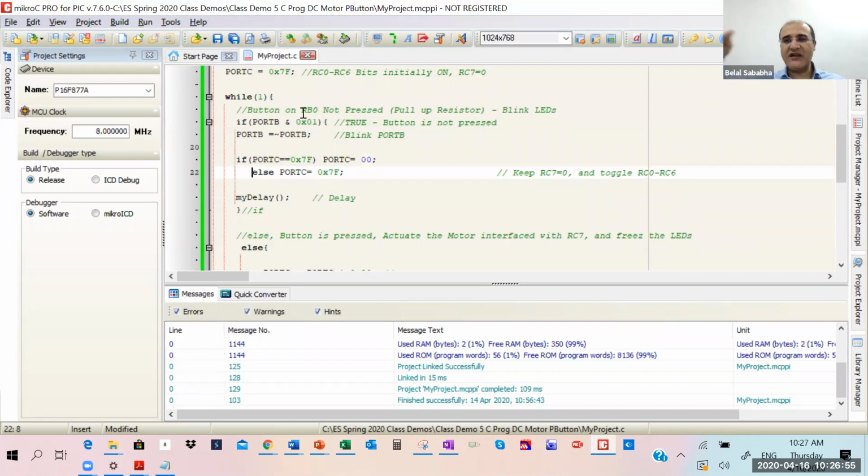So if you keep your finger on the push button for a long time, that allows the program counter to finish all the instructions, come back, check the button, and it will do what you want, but after a delay, right? It's not gonna be an immediate response. Okay, so this is called polling. We talked about it in class when we were back on campus. Polling. We check push button 1.